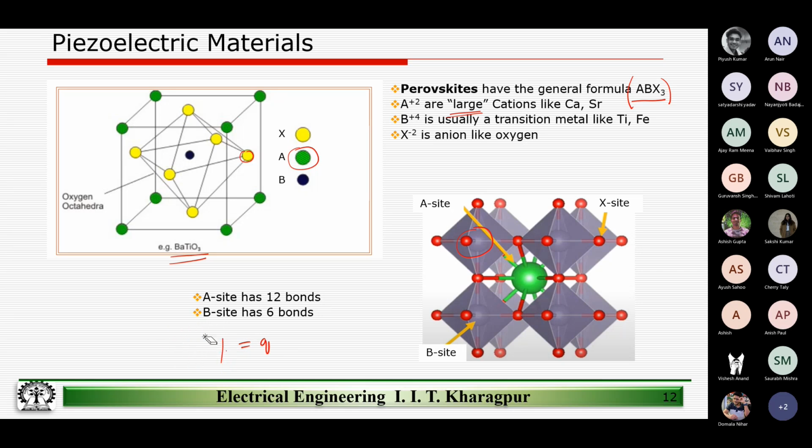So the goal is to realize crystals or crystal structures which will behave in a way that on the application of a force, the symmetry, or the way the ions are bonded to each other inside the material, will be disturbed and dipoles will be formed. Even though the net effective charge inside the material remains zero, which is what I think one person pointed out, a net electric field will develop, because the positive charges will move to one side and the negatively charged ions will move to another side, forming electrical dipoles. So we will try to realize or manufacture material which will have this behavior.